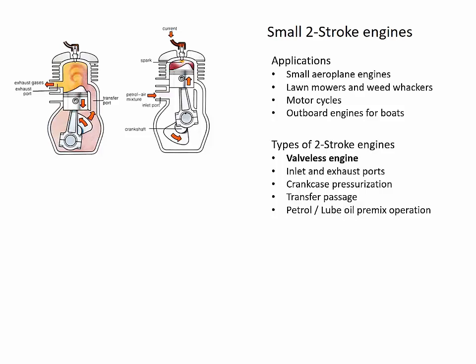So as the piston moves downwards, the air and fuel and oil mixture will be forced up through a transfer port into the actual combustion space. And at the same time that that is happening, exhaust gases will be forced out of the exhaust port. So the piston actually acts as the valve in this particular case. It's important to note that the petrol is mixed with a premix of lubricating oil because there is no lubrication oil system as such.